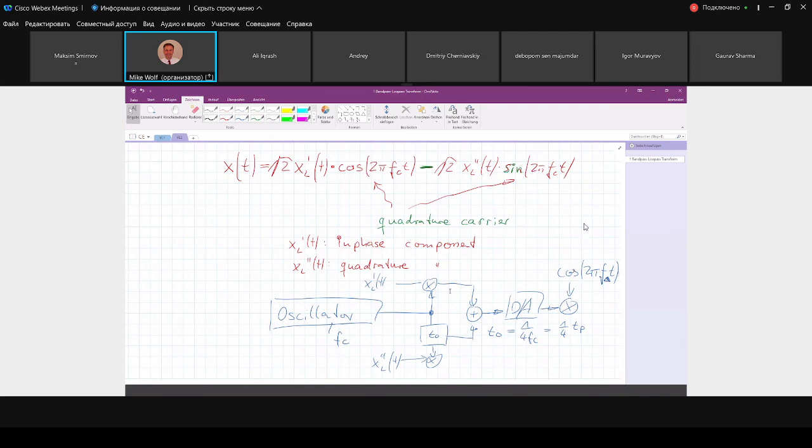The reason is you want to use digital signal processing. You want basically a perfect 90-degree phase shift here, and you cannot ensure this in the analog domain. If you do this in the analog domain, it's often said that you have an imbalance between the quadrature components, because the realizations are not identical, and the multipliers here are not.